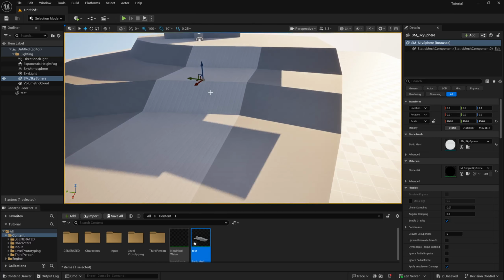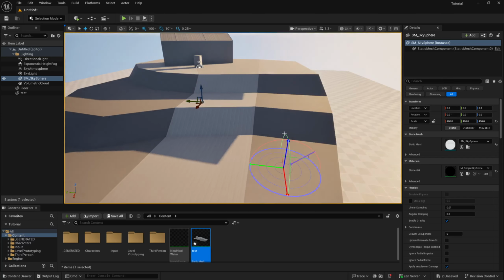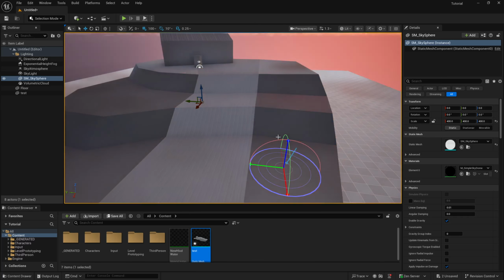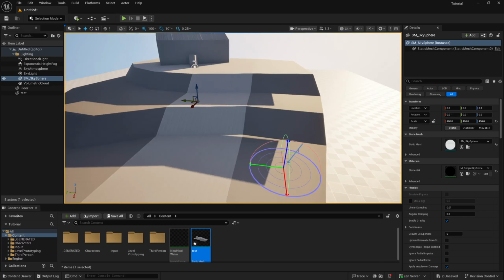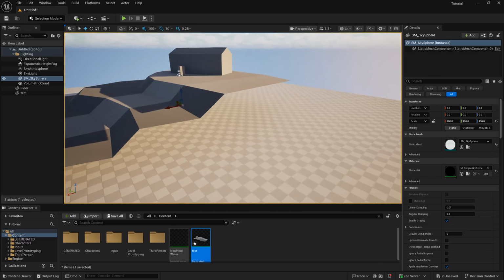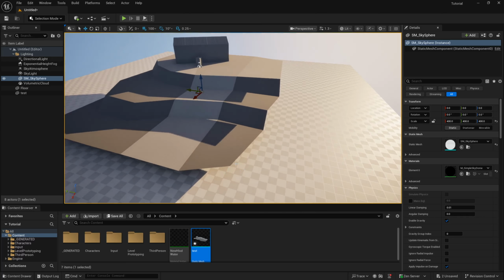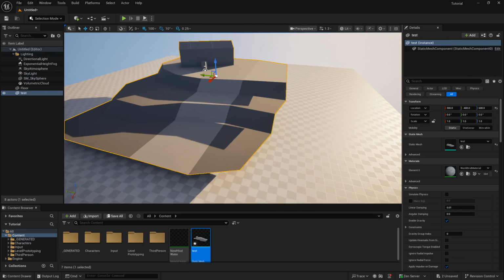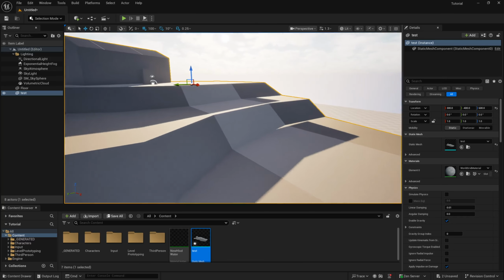You can see here, this is actually caused by no backfacing, I believe, on this particular piece. So there are some limitations. When you don't have backfacing, you can't just leave it bare, open to the sun. A lot of games or projects in the past, you'd just create blocking mesh to fix that, but you could make it double-sided render as well, and it'd probably fix it, if that's what's going on there anyways.